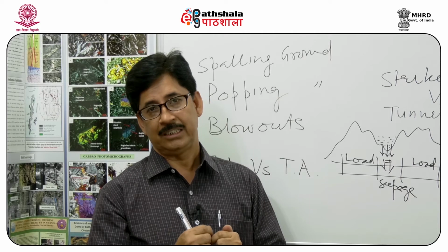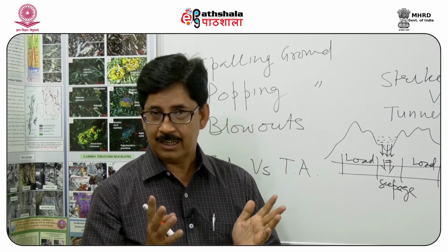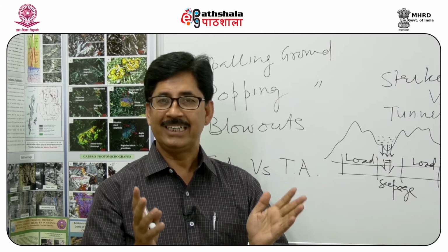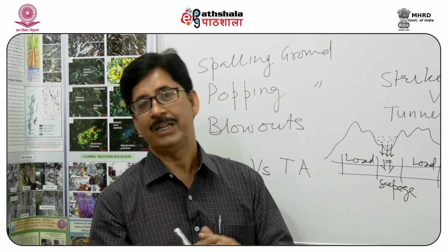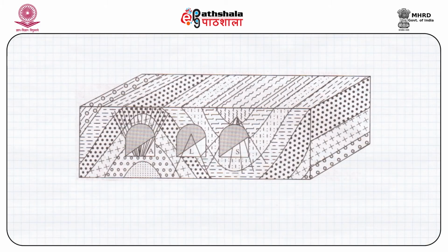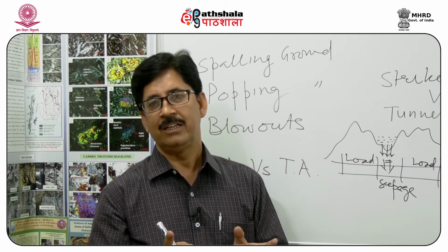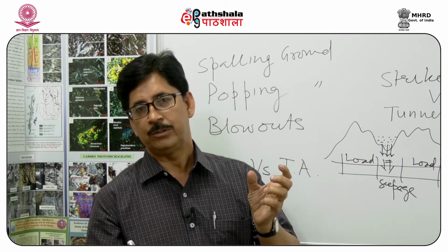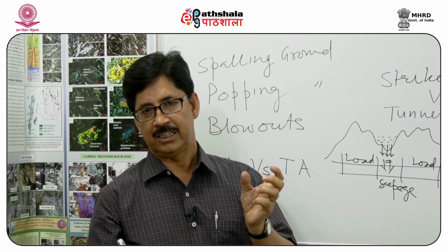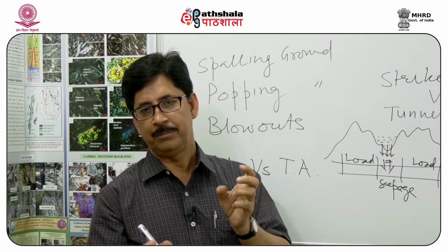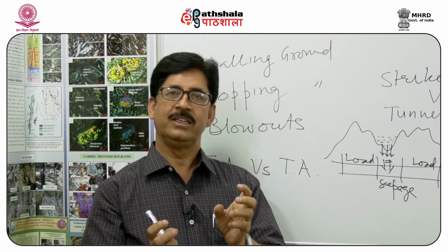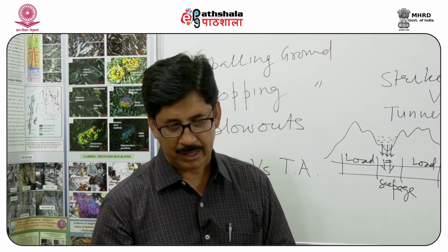Whatever groundwater is seeping through the fractures in the rocks will get concentrated along the synclinal zone as compared to anticlinal zone. So we have to see what is the best option left with us. It is better to have tunnel in between the two, that is anticlinal zone and synclinal zone. In the mid part of the limb, if we can drive a tunnel, that is the best option.